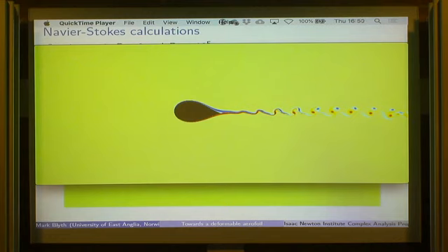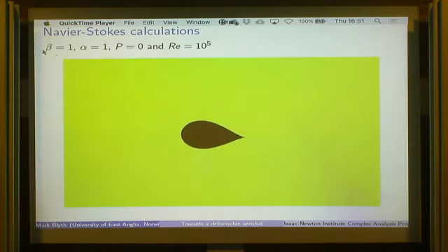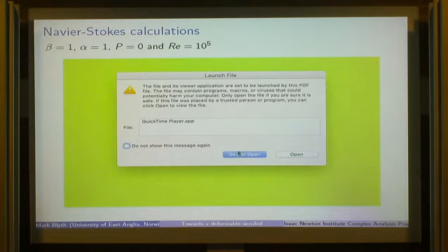Does this calculation allow the airfoil to deform? That's a good point. No, it doesn't. I should be clear about this, I was going to say this at the end. What we've done is taken a static equilibrium shape and then treated it as a rigid body in a DNS solver. So it's not correct, but it's the first thing to do.